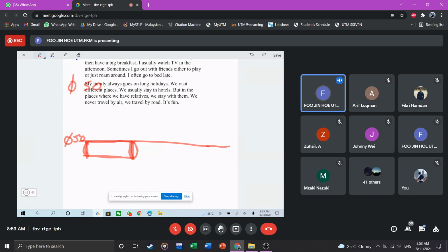Forever, the maximum size is 50, so it can only be smaller, not bigger. The maximum value will be 50.0. This is the shaft basis system. We fix the size of the shaft, and then the variation is on the hole.